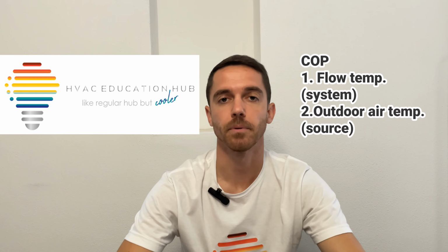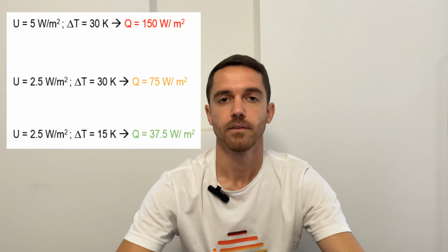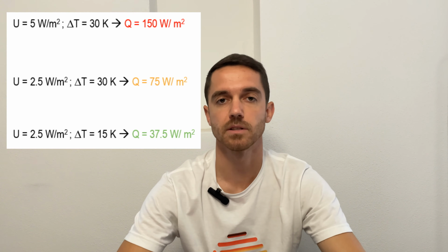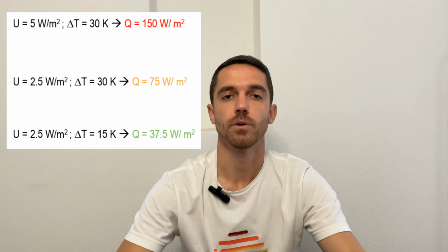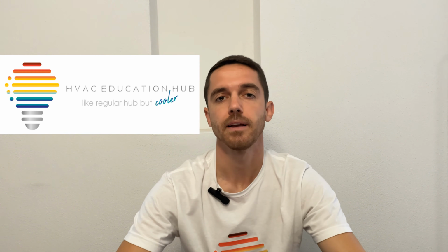So people say that if you have a non-insulated house, a heat pump cannot work in your house. This is not true. Of course, if you don't have good insulation, if you have high heat loss, as we covered in the heat loss episode, and you have a higher U value, your running cost will be higher. But COP is not about that.